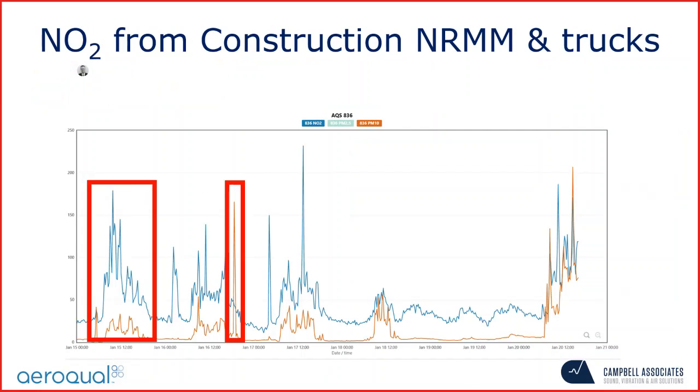As I mentioned before, one of the other areas that's been used extensively in the UK is adding NO2 measurement into our Dust Sentry, which turns it into an AQS. And as you can see, at the first peaks that we've got there, NO2 has gone up at the same time as the particulate, which shows that it's probably a diesel vehicle.